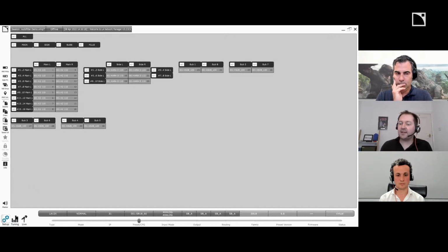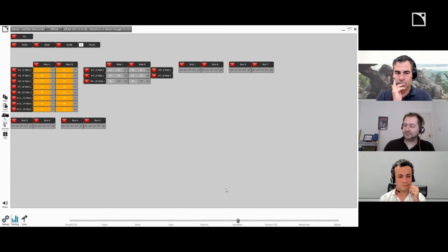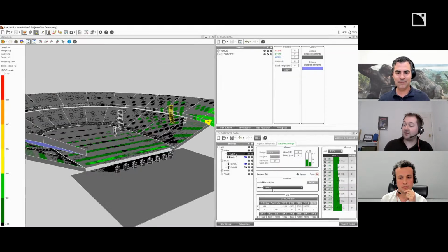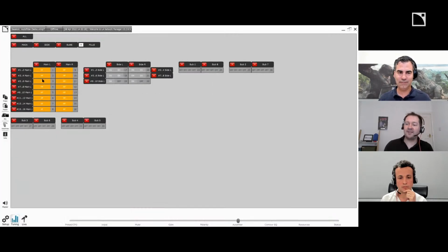The reason being is if we go back to the tuning page, you'll see I had this selected. We've tuned the system. We decided we couldn't afford the additional latency, so we went to the reduced latency mode, so it's HF filters only. Now, right before the show, when we update with the atmospheric conditions, we don't want to introduce any potential latency changes by accident. So you notice in Soundvision, the mode is still default, so full optimization, but we don't update that in the synchronization.